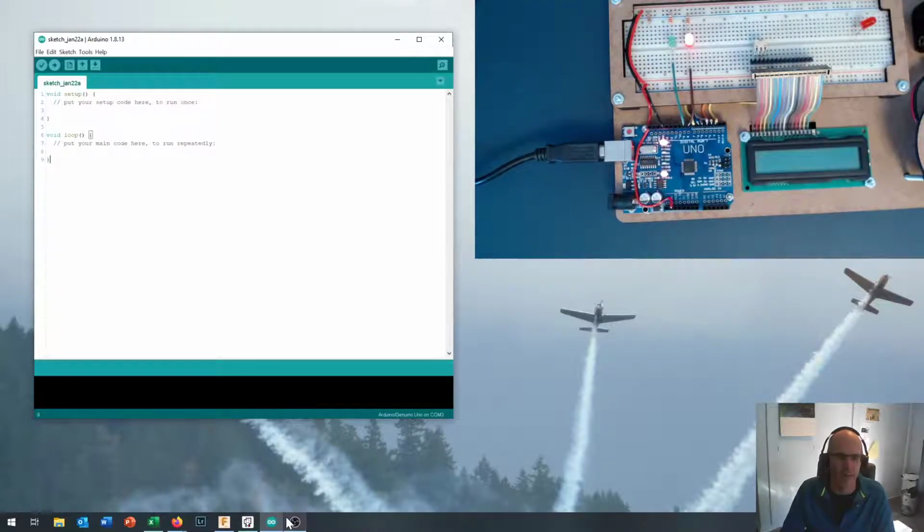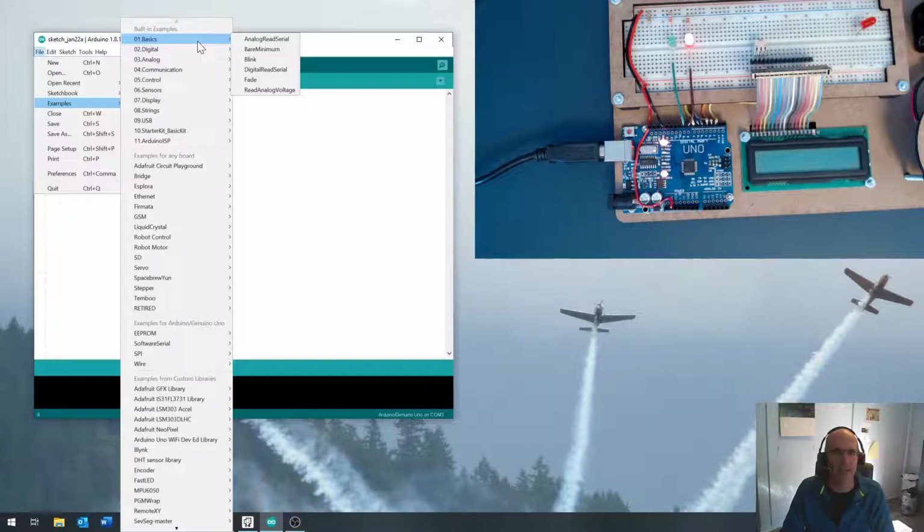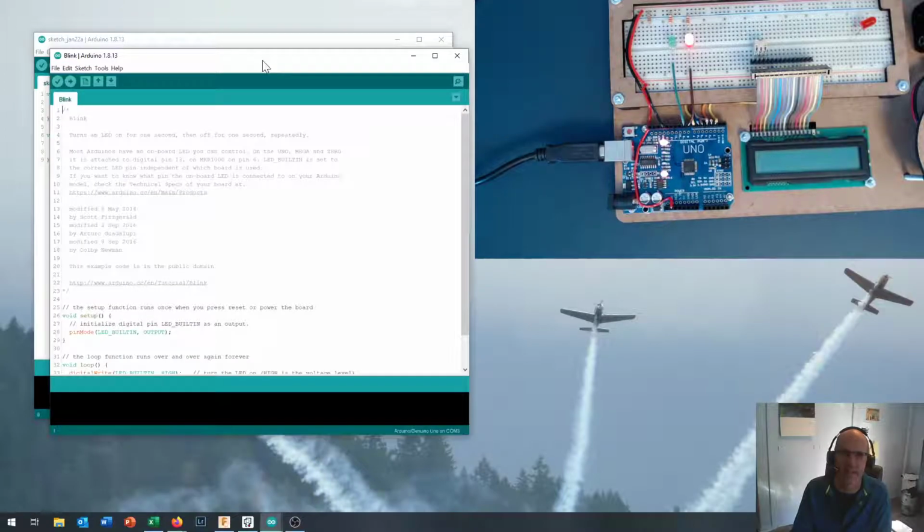All right, now what we're going to do is we've got code right in here, and we're going to run a test. Before we do anything else with our Arduino, you can see right here our code is going to do nothing. The Arduino has a ton of really useful examples that come with it. So go to File and Examples, and in your example settings, come to Basics, and there's one called Blink in there. And you'll recall that there was a blinking of the internal LED on our TinkerCAD Arduino. This is that same code right on here. It's already baked into your Arduino.